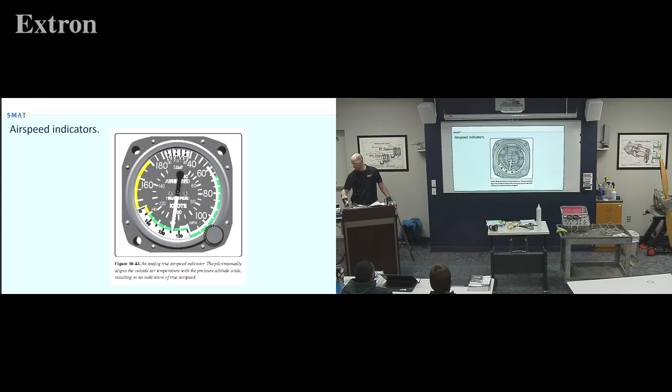Alright, quick review. What is this actually measuring? On the very basic level, David. Pressure difference between outside air pressure, or like the ram air pressure, and static pressure. Yeah, ram air or pitot we call that. Ram air and static, which is just outside air. That is correct.